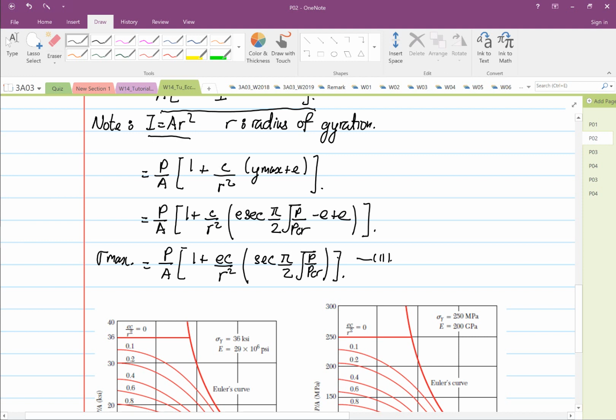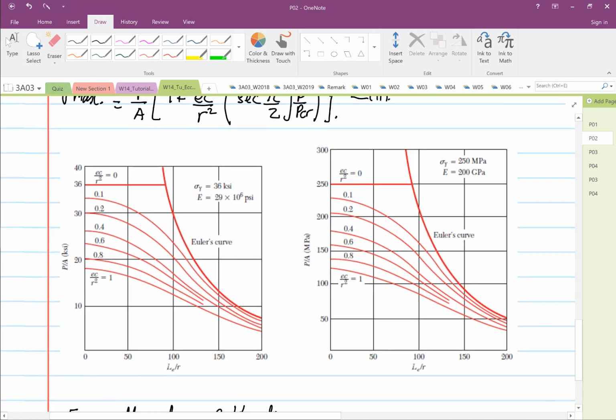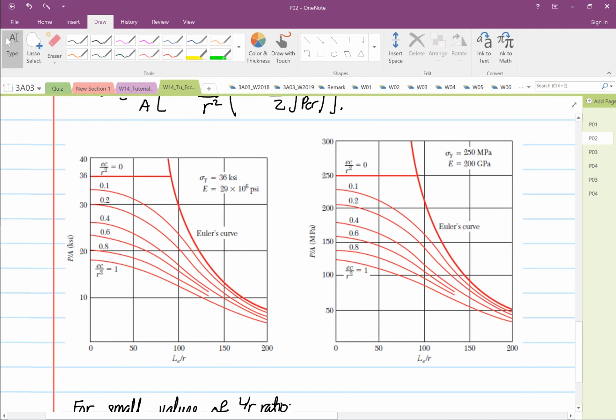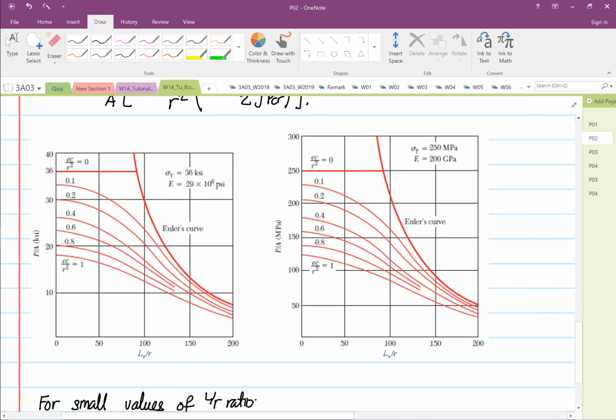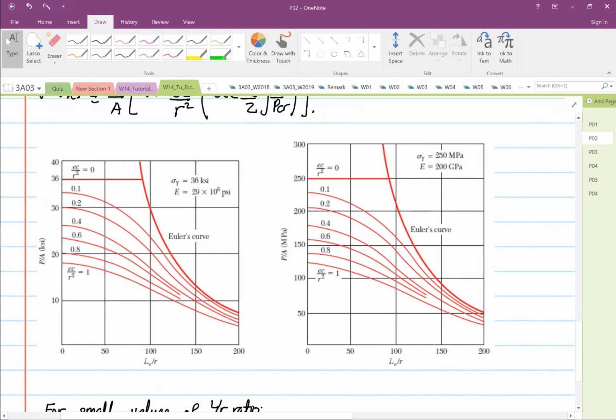So from here, you're going to use a table, which we can get from the Materials Handbook in terms of buckling. This table, or these graphs or figures, is acquired from experimental work, and this is specifically for yield strength of 250, Young's modulus 200.